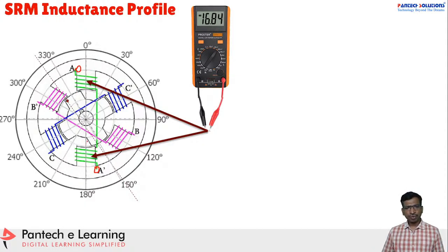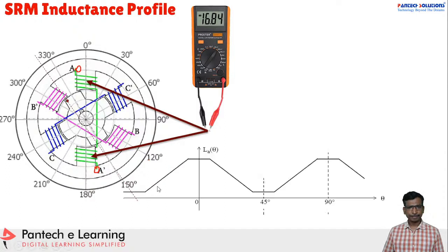So now what will happen? Manually you have to switch the rotor. Here the rotor diagram has been mentioned. For example, my LCR meter has been connected across the phase A terminals. Now you have to rotate the rotor from the original position to the aligned position.